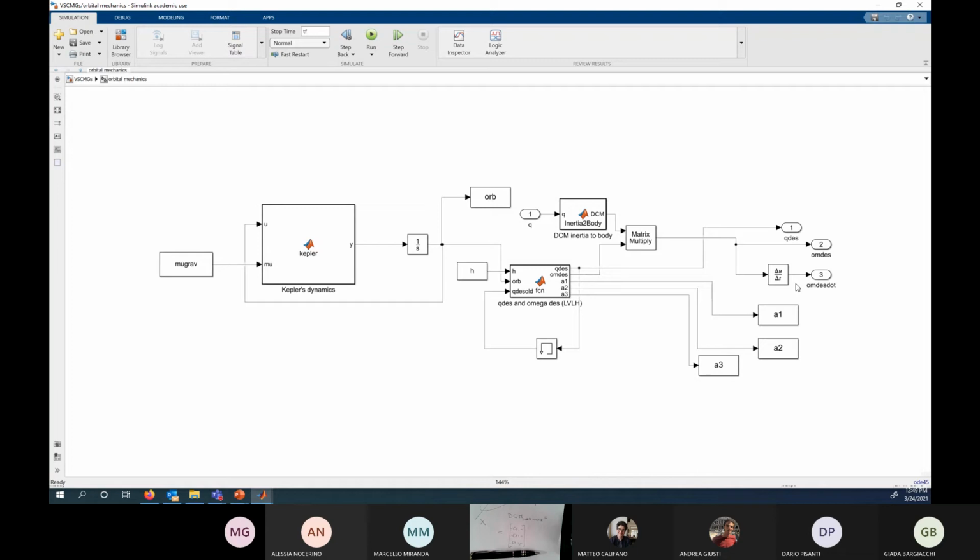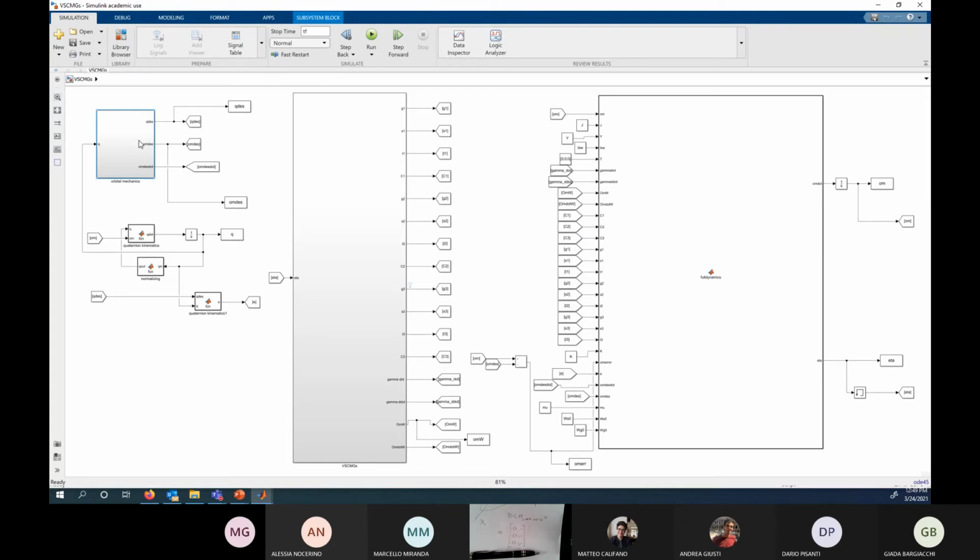Just keep it in mind that when I was working on my master's thesis, the one that I shared with you, I remember that I was insisting on taking time derivatives of variables, and I was cautioned not to do that, because in real life, you definitely don't want to take the derivative of a noisy signal and then use it for control purposes. It creates big problems.